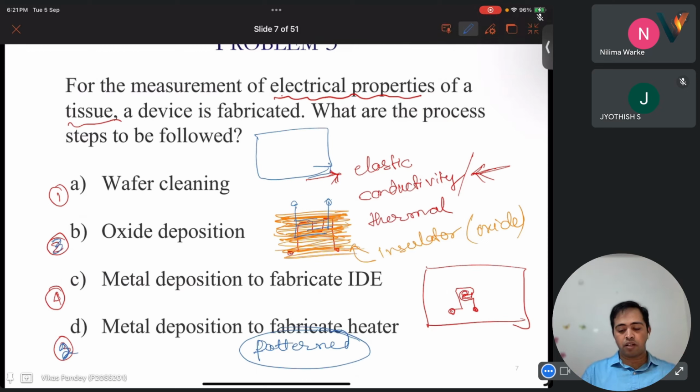Here the whole thing will be metal and some pattern is cut out from it. It is put above the silicon wafer. When the metal deposits, it will deposit throughout, but only the pattern will get deposited inside. On the other part it will deposit on the mask, and we can clean the mask.